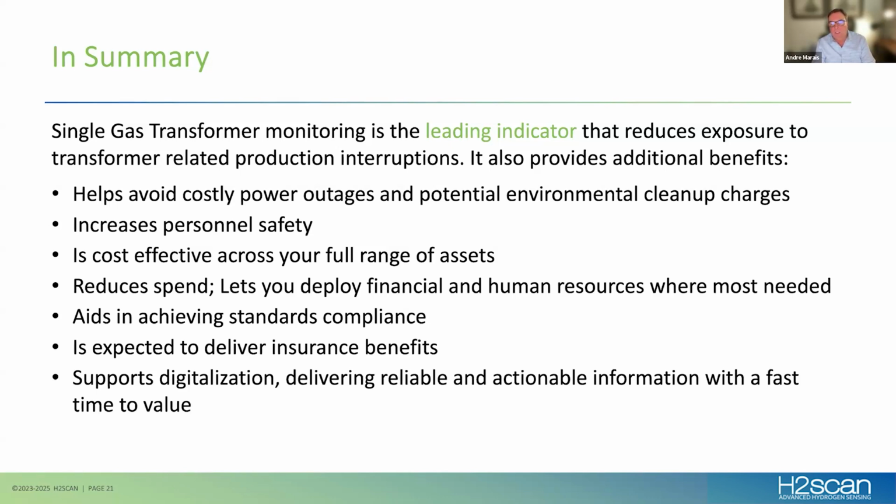We're able to install these on a live transformer. You're not required to take the outage. On a transformer, of course, that does depend on your work standards. It does depend on the proximity of the drain valve. These sensors are installed on drain valves. And it does depend on their proximity to conductors and to bushings. And if you're installing it on the top of the transformer, yes, you will require an outage, but it's very brief. There's not a lot of mechanical or civil works required to install these products.